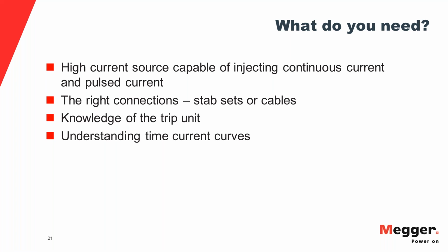You need to have a good knowledge of the trip unit. You need to know how to operate the trip unit to set the right delays and the pickups required to do the test. You need to understand the time current curves to be able to validate the results that you get.